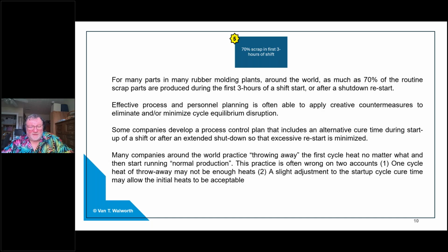And so you're either trying to reestablish it, getting it hotter, or you're trying to reestablish it, letting it cool down from having been closed overnight, over a weekend, over something, and everything is just a little too hot. And it takes time for that equilibrium to be reestablished around the press and in the environment where you're working. And so during that reestablishment of the equilibrium is when a lot of scrap can happen, good or bad, whatever it's doing.